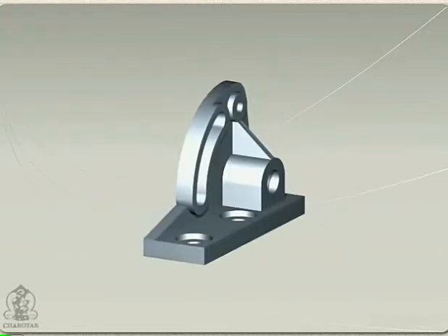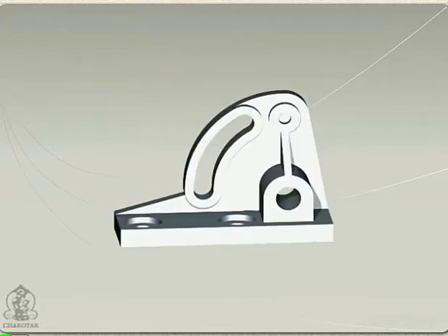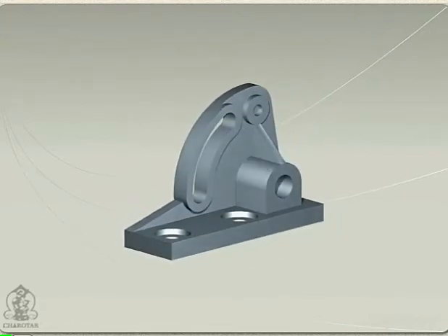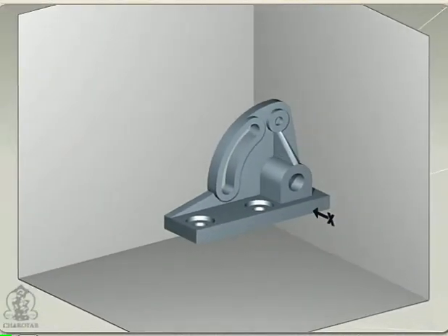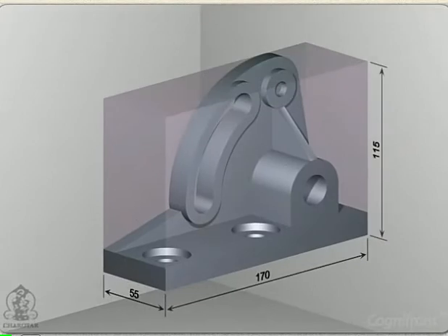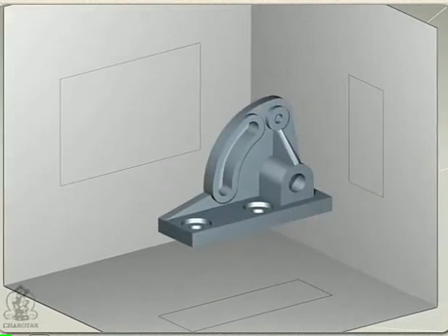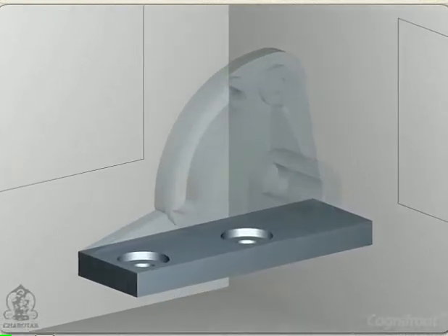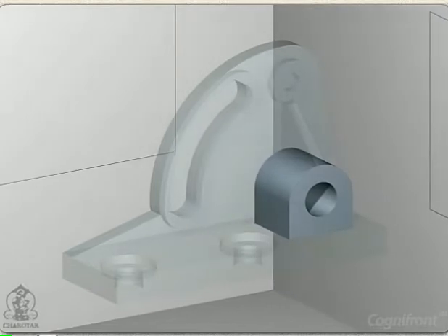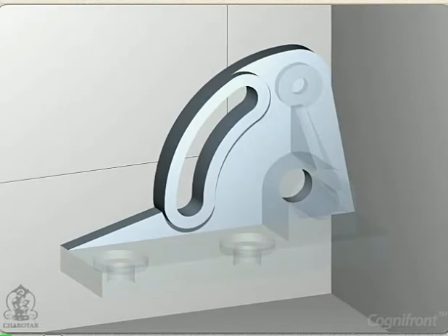Hello, today we will generate the front view, top view and left hand side view of this object as seen in direction X. As the first step, we will draw the bounding box of this object and determine the bounding rectangles of projections in their respective planes. Observe the primary parts of this object: base plate with spot holes, semi-cylindrical extrusion, boss hole, rib and slotted vertical plate.